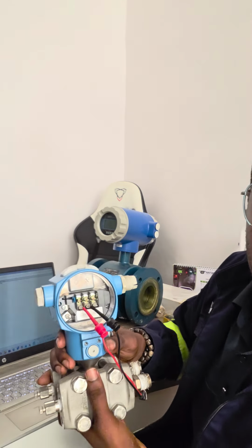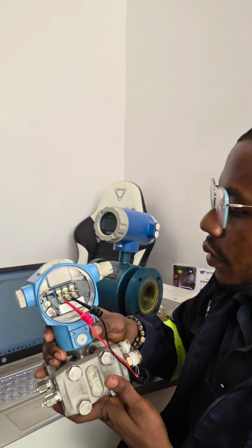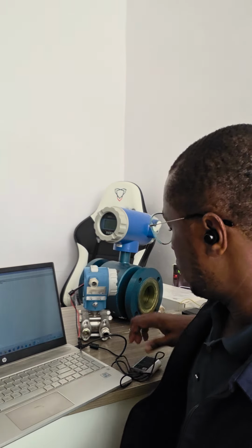Now we have your positive, negative, 4-20 milliamps output test. So we connected it to 4 to 20 positive and negative. To remember, this is a resistor for you to connect properly to your USB Hart modem, by pulling or not pulling the 250 ohms resistor, depending on how your Hart communication device works with your model. Do you understand? If you don't understand, this is for professionals, and if you want to learn more about this, you have to call us for that.